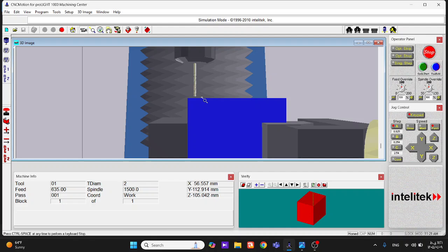You can assign it like that, but sometimes they will put a paper here and the operator starts coming down, and the paper is moving till it sticks between the tool and the surface. That will be the 0 point in a real way, but normally you can use 0.002 as exactly the height or depth of the paper.